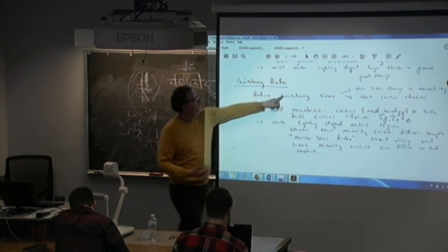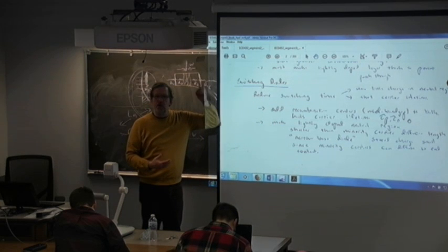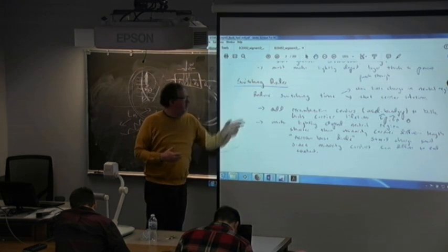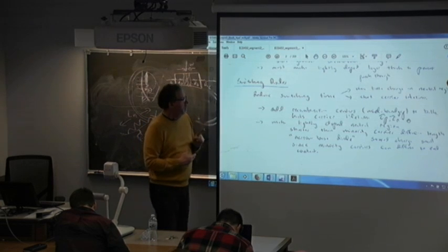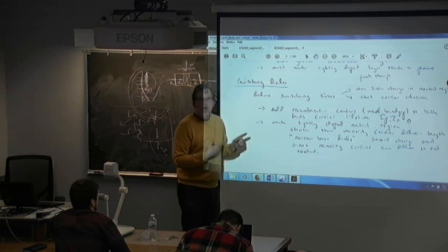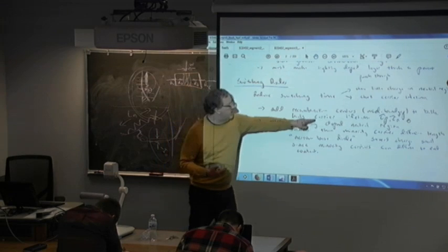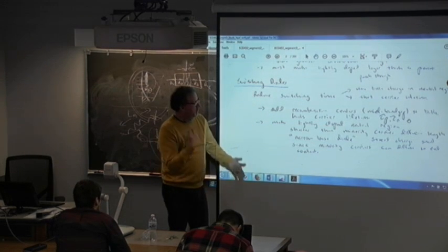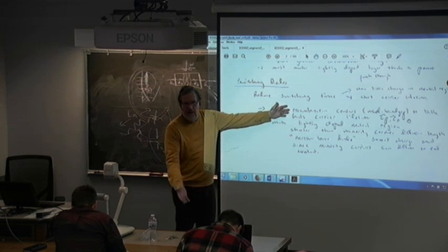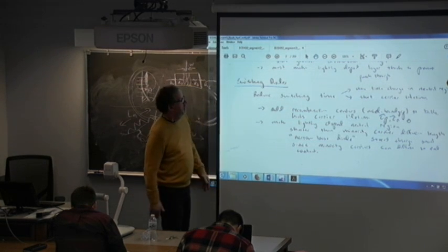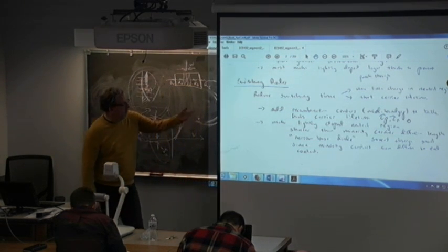So if I want to make a fast switching diode, sometimes I might want to use poor quality semiconductor material on purpose. So sometimes good material is not always what you want. Here it kills the carrier lifetime, so things recombine. Now this would be a lousy laser, a lousy LED, but for a fast switch, I want to do something in the terahertz, maybe this will work.